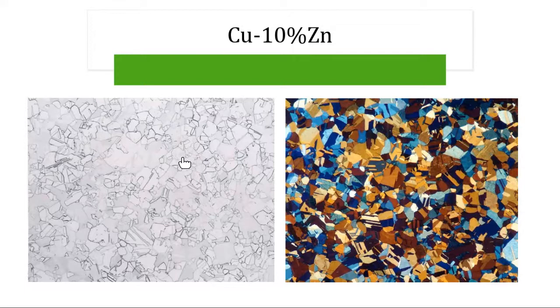With a colored etchant, since it is highly dependent on crystallographic orientation, you go to that same sample and look how small some of these grains are. It's able to pick up those grains.